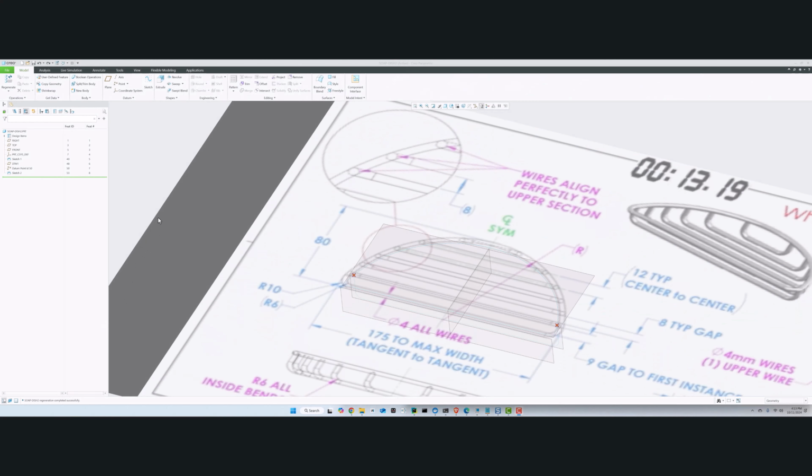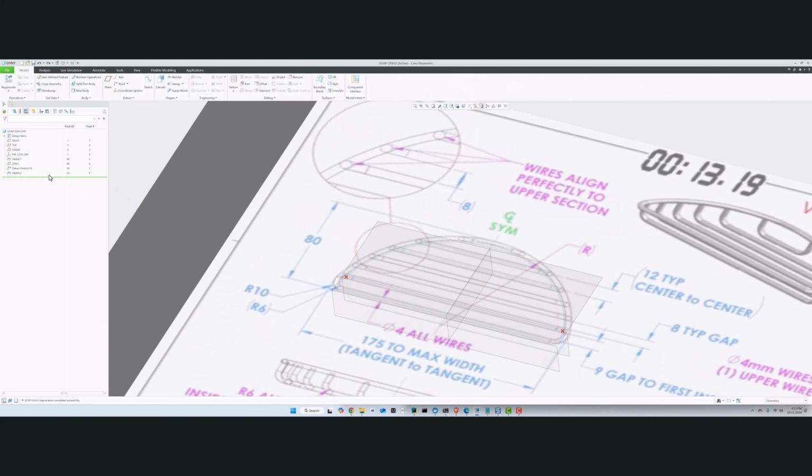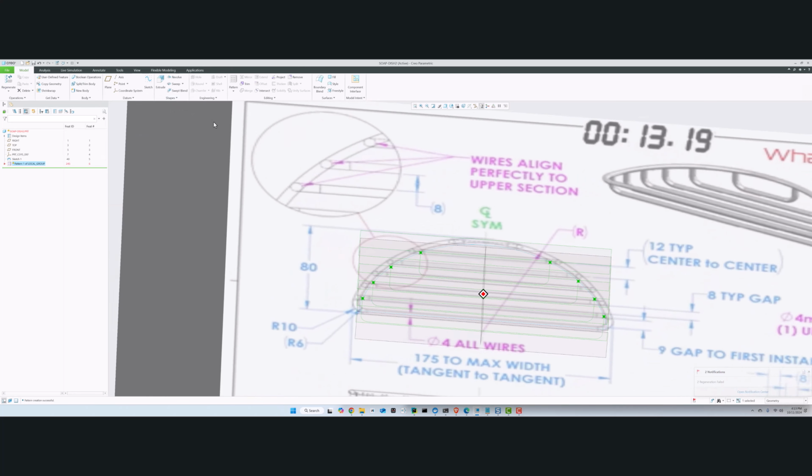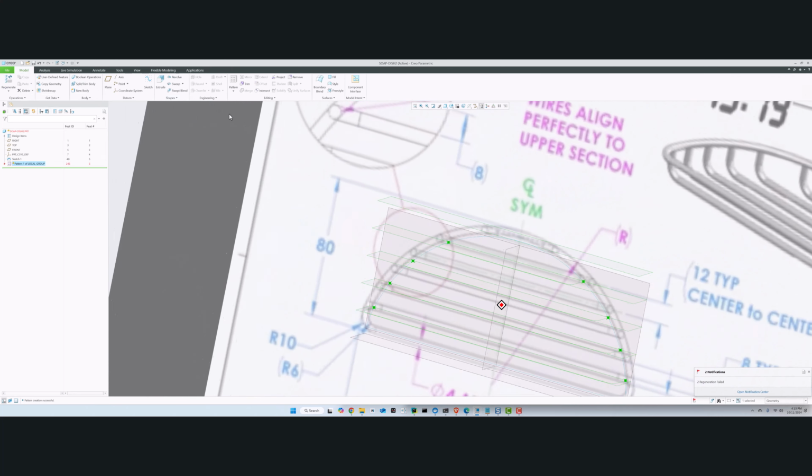Okay, now that we have our sketch defined, the next thing I'm going to do is take all this and put it in a group. I'm going to do that because I want to use the pattern feature, and I want to change this dimension to 12. So just type in 12. I'm going to put the count here in 5. And let's see if Creo generates us those parametric sketches. It does. See that here?